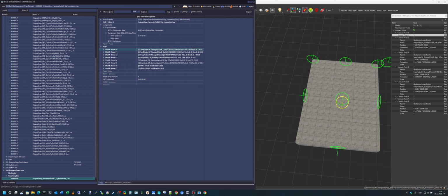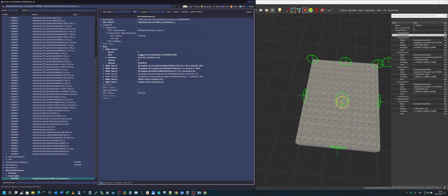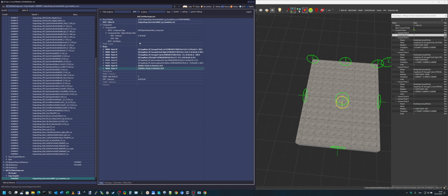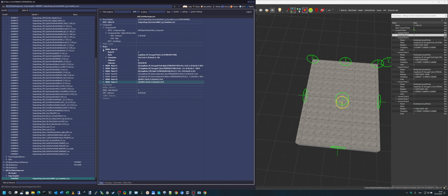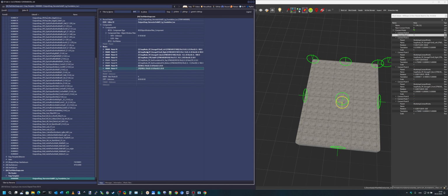So we don't have 0, 1, and 2 now. We have 3 followed by 6, 7, 8, then 5, 4, and 9, 10, but we do not have any duplicates. So these IDs are now okay. But after you change all the IDs of the other nodes, you also have to change this next node ID. If your largest number here is 10, you can put this at like 17 if you want, and it would still work, there are no duplicates.